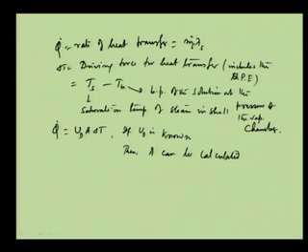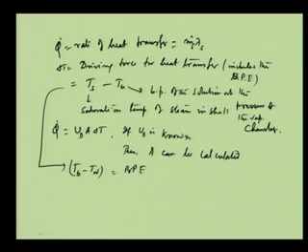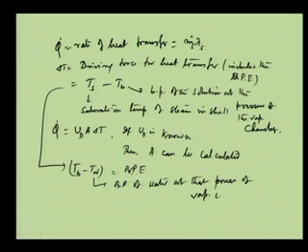If we see what the boiling point elevation is in this case, it will be T_b minus T_w, that is nothing but the boiling point elevation. So, this is the boiling point of the solution, and this is the boiling point of water at that pressure of the vapor chamber. Okay. So, this is nothing but the boiling point elevation that we have already discussed. Fine. So, this is the basic concept.